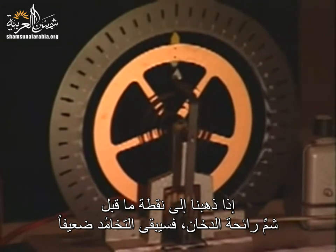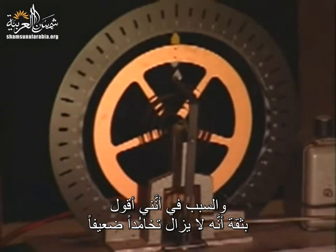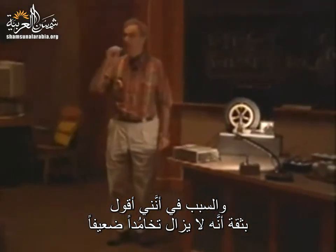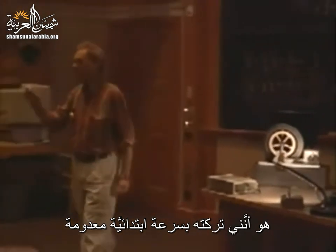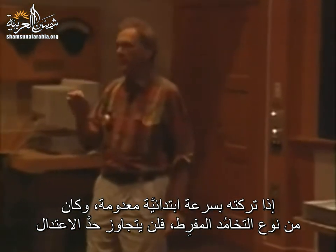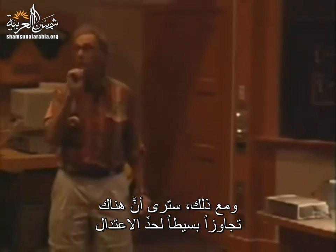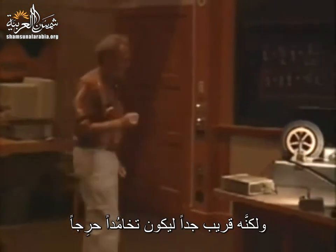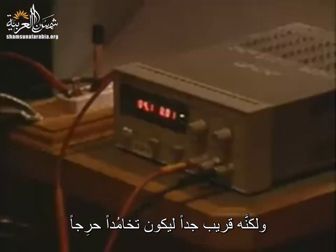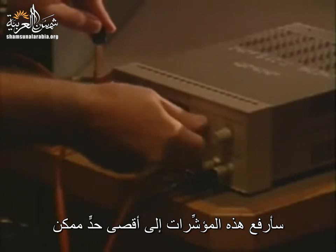But if I go to the point where you just don't smell smoke, then you're still underdamped, but you get a huge amount of damping. And the reason why I can say with confidence that it's still underdamped, I release it at 0 speed. And if I release it at 0 speed, and if it is overdamped, it can never overshoot. And yet you will see that there is a minute overshoot. So it is still underdamped, but it's getting very close to being critically damped. And so I will jack this up to the maximum possible.